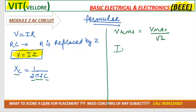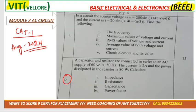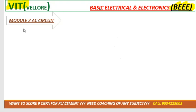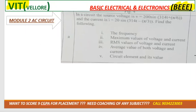Similarly, IRMS is always equal to Imax divided by root 2. Whenever they give you the equation, they'll give you Vmax, and we want to convert it into RMS. Clear? From this you can get it. If they give you something like 60 volt in a statement, that is the RMS. But whenever in a numerical they give you the equation, they'll 100% give you the maximum form. Clear?